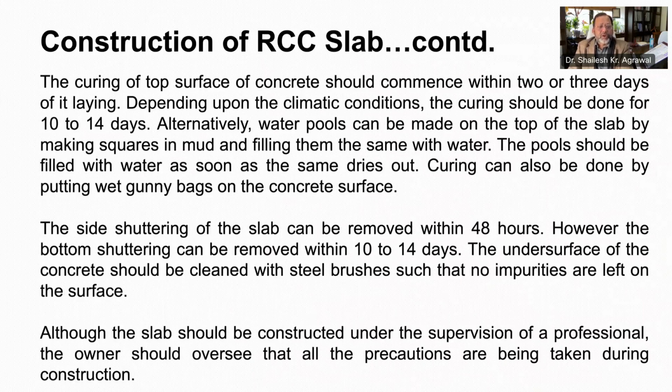After laying the concrete, the curing of top surface of concrete should commence within 2 to 3 days. As per climatic conditions, the curing should be done from 10 to 14 days. The prevalent method of curing is to make water pools on top of slab by making squares in mud or sand and filling them with water. The pools should be filled with water as soon as the same are dried out. Curing can also be done by putting wet gunny bags on the concrete surface.